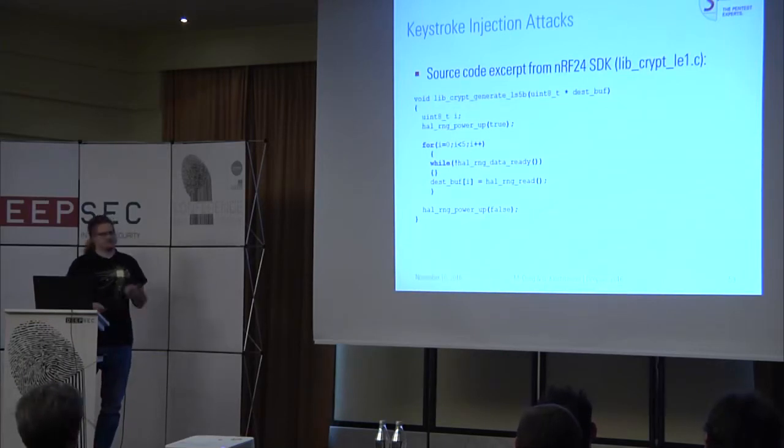So the keyboard just sends a package with a random counter, and the dongle says, okay, I take this counter, whatever it is, and does not synchronize in any way. If we reuse that counter, it's okay for the dongle too. The dongle does not have any list of already used counters, it just uses the counter again and decrypts the package using that counter.